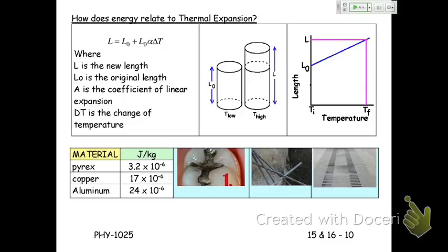And what happens is, first of all, if they used any old thing, it would be a real problem because your tooth expands and contracts with temperature, and that filling will expand and contract with temperature. And if they don't expand and contract to the same extent, and the tooth expands more, then your filling will drop out when your teeth get warm, or if the filling expands more, then the filling will crack your tooth as your mouth gets warm.